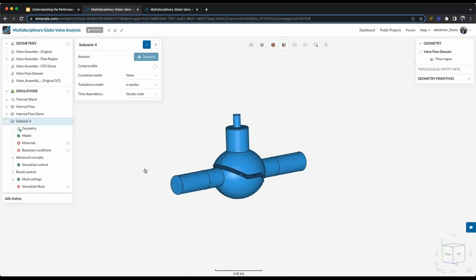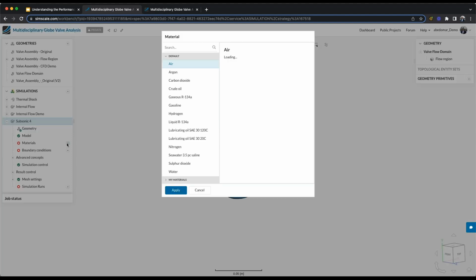So from here, when we create a new simulation, you'll see on the left-hand side on the navigation tree, the simulation setup shows up. And the red circles here are indicating missing inputs for us to define, in this case, the flow problem overall. So the first step is going to be to fill in these red circles and turn them into green check marks by defining the problem.